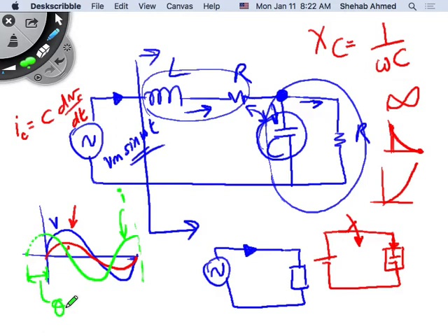Maybe at the end of 214 you took that a little bit. The power factor angle, have you heard of that? So you've heard of that? Okay, so this is called the power factor angle. It's the angle between the voltage and the current, right? So if the impedance is an equivalent capacitive impedance, the current will lead the voltage because of this equation, right? And the angle between the zero crossings is the power factor angle.